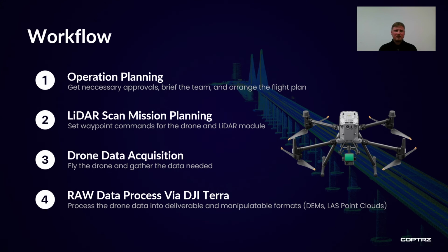That gives us an estimated point density of around 200 to 300 points. When I mentioned spec earlier, that's a really useful bit of information to take: will that give me my desired results at the end of it? So we set our flying height, we have that live on screen to give us the estimated point density, and then DJI Pilot 2 will do the rest for you.